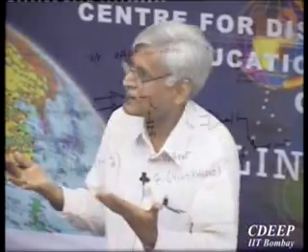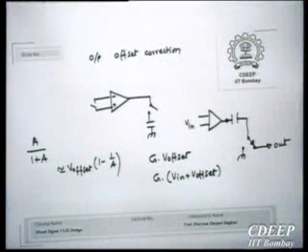If you have a feedback for unity gain configuration, then this op-amp needs to be compensated. Right? Have you all done this in the other analog course on op-amps? You have gone through compensation. So you know that if there is feedback, you need compensation. Now this is a large capacitor and it reduces the bandwidth of your op-amp. You put a Miller capacitor there, so it makes your op-amp relatively slow.